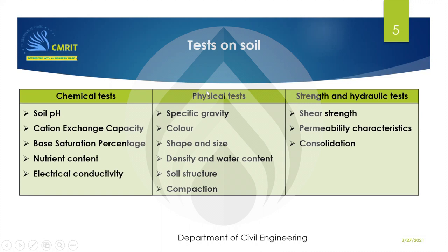With respect to an important parameter, definitely it's very, very important, because these days we are having many materials that have been used as a substitute for soil. For example, fly ash, pond ash, and even as a stabilizer we try to use other types of mixes, and even mine tailing waste or rubber, and many things we keep using in order to modify the soil. So specific gravity is an important parameter because it even determines the mass of the structure itself.